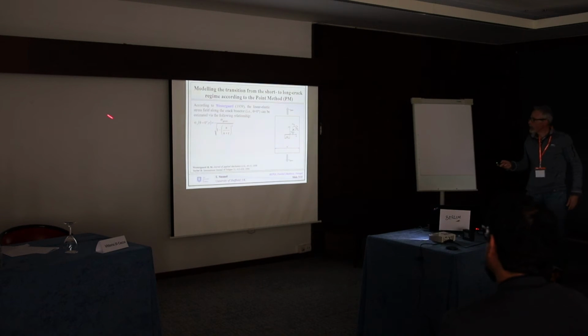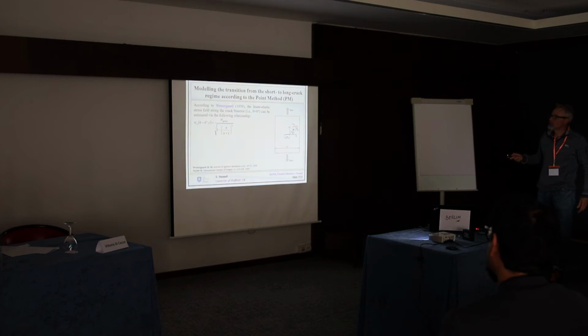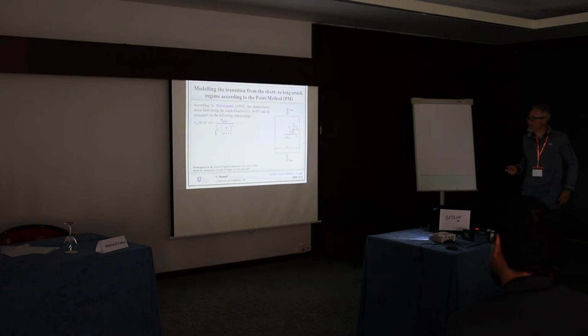Because if you go back to Westergaard's solution published in 1939, you have basically a crack in an infinite plate loaded in tension, and a nice closed form solution which gives you the distribution of the stress, which is singular, on the x-axis, that is along the crack bisector.